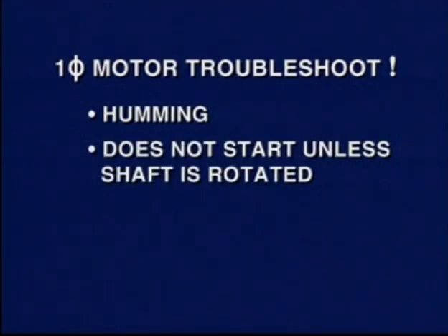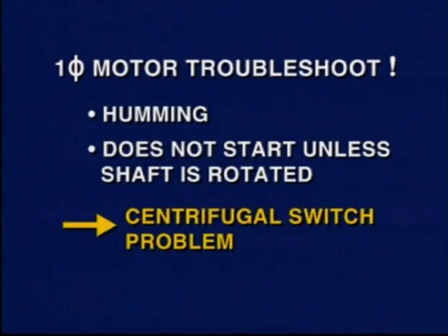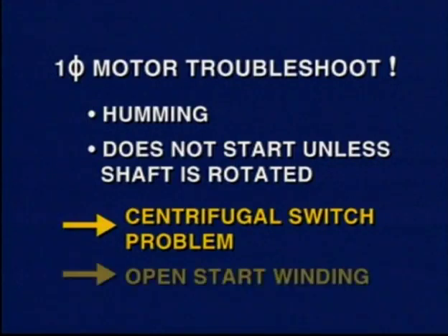If you are troubleshooting a single-phase motor because it is humming and doesn't start unless you rotate its shaft, then the cause of the problem is the centrifugal switch not operating correctly or an open in the start winding.